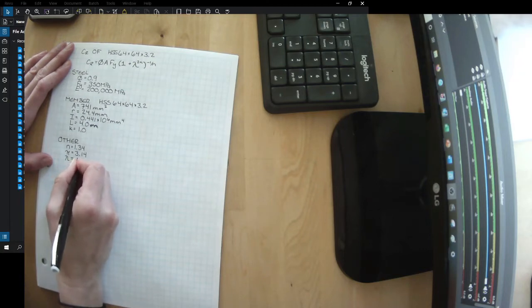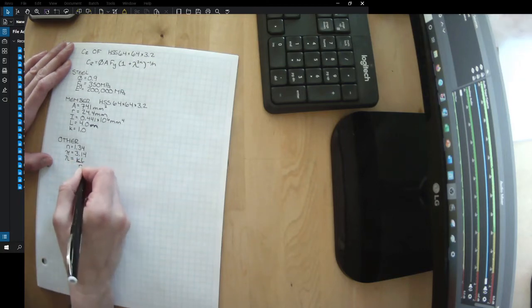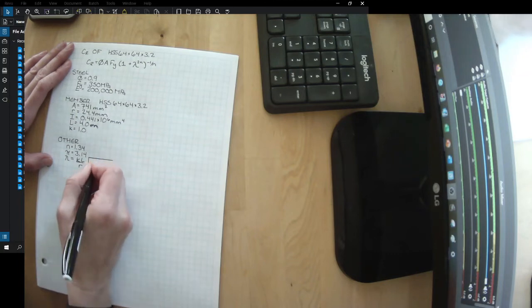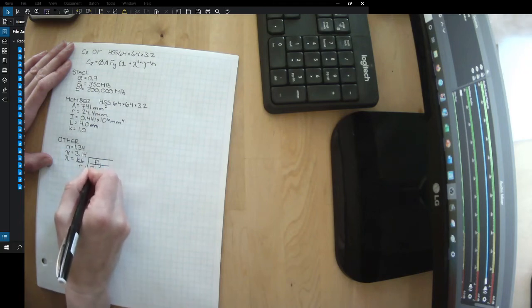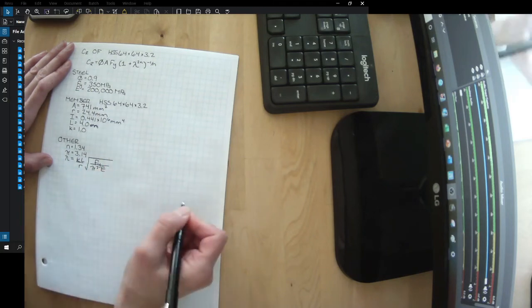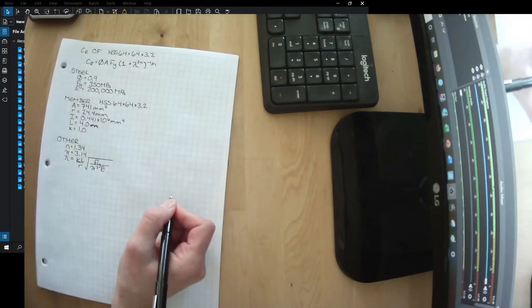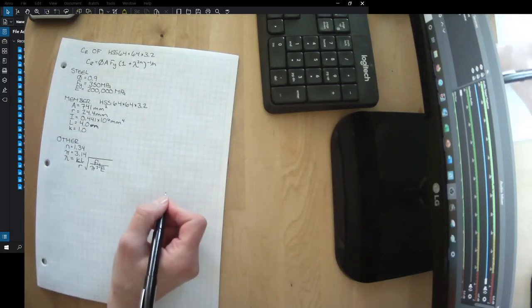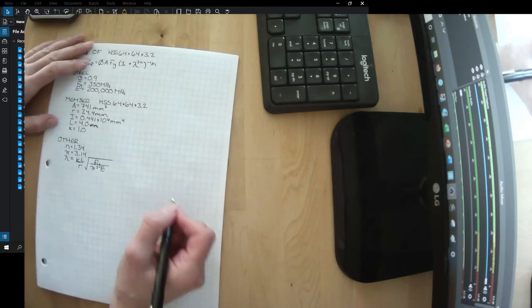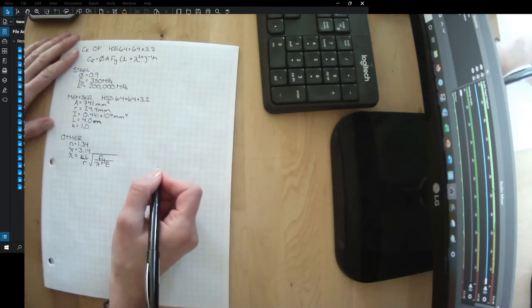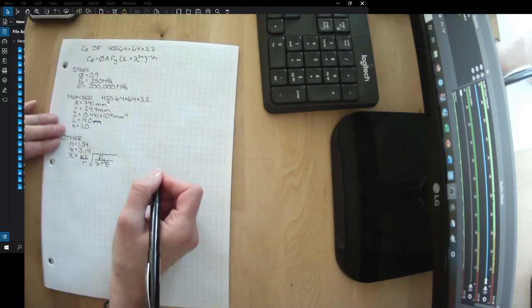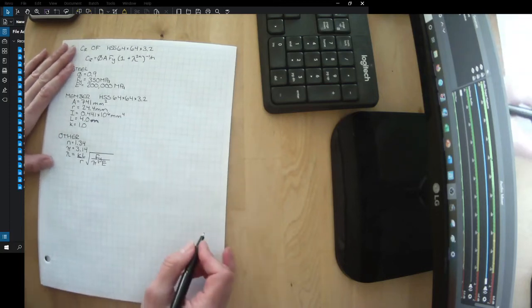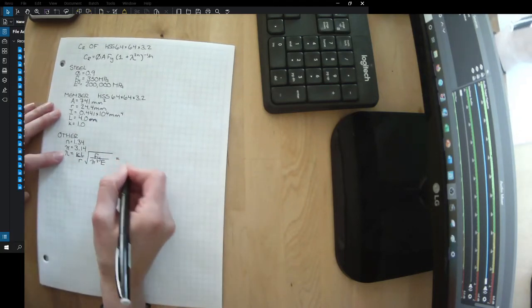Lambda is KL divided by R times the square root of Fy divided by pi squared times E. This is derived from the critical buckling equation. There was a way we could do it where we could go through and calculate the critical buckling and then figure out the stress associated with the critical buckling. Or we can do it this way. I'm going to recommend doing it this way. And so just follow along. You'll see what I'm going to do. Let's calculate this critical buckling.